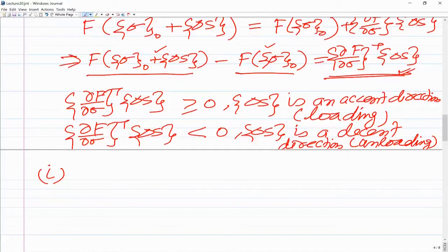So every time you do the calculation, you are going to update that variable, whether the Gauss point is elastic or elastoplastic. Initially, of course, all Gauss points would be elastic when you start increasing the loading. So initially all points will be elastic. You will denote the status variable as one for all the Gauss points, all the elements, and subsequently, based on this analysis, you will be updating it. When it is crossing the initial yield surface, then the status of that Gauss point would change from elastic to elastoplastic. So you will have to store all these variables.